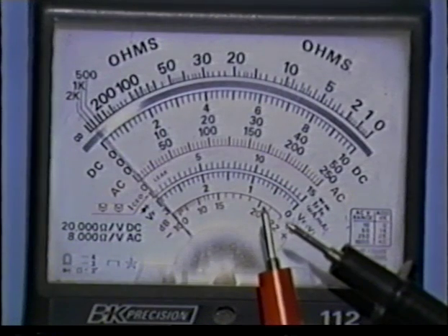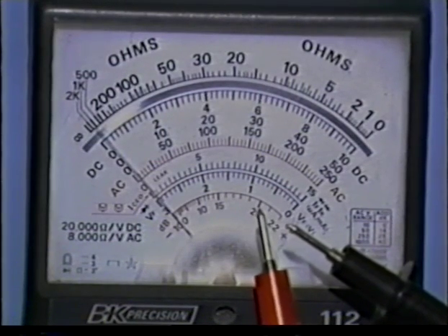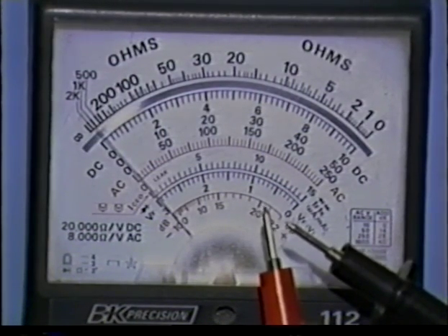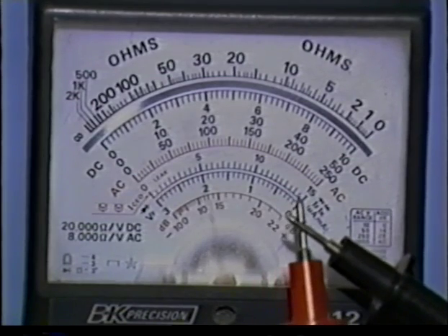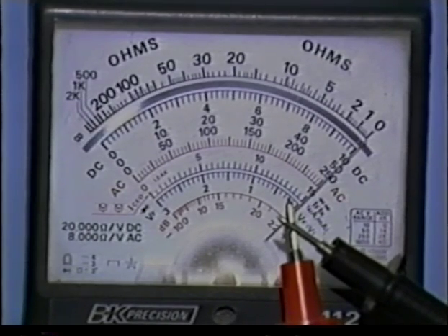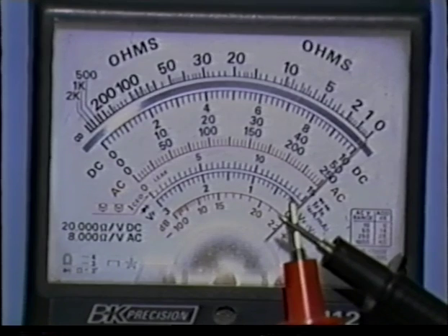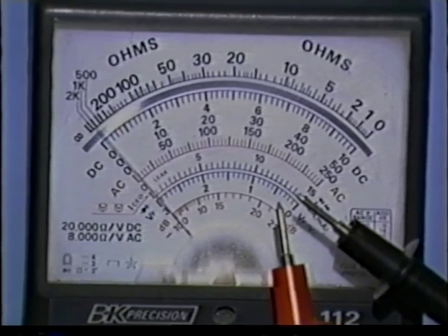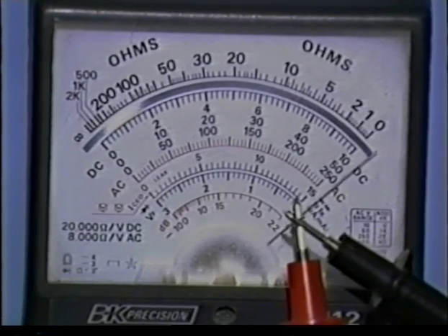An ohm meter also demonstrates an open and closed circuit. If we touch the test leads of this ohm meter together, it shows 0 ohms or 0 resistance. There is a complete path through the test leads. When we do not touch the test leads together, an ohm meter would show maximum resistance, or an open circuit. This action is a basis for electrical tests with an ohm meter.